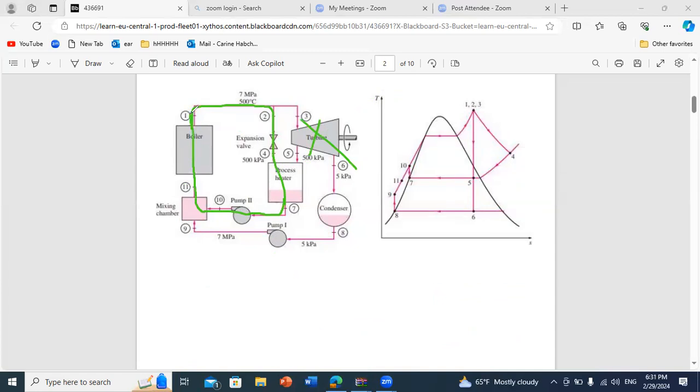Okay? And in this case, if I have an ideal system, I will use a big amount of energy. Why? Because if you want to calculate the useful energy here, what is the useful energy? It's the energy that I am able to extract at the process heater. And if I consider the energy balance of my cycle, I can write Q dot into my boiler minus Q dot process that I am extracting.